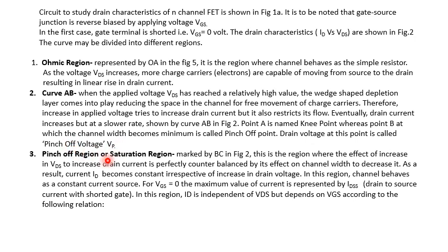Now the pinch-off region, or the saturation region. This portion is denoted by BC in figure 2 in the previous slide. In this region, at a particular voltage Vp, which is shown as the pinch-off voltage, the two effects of increasing VDS come into play. The first is that current will try to increase, and the second is that current will try to decrease.